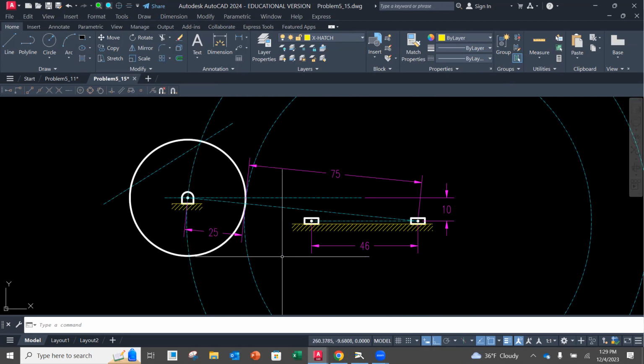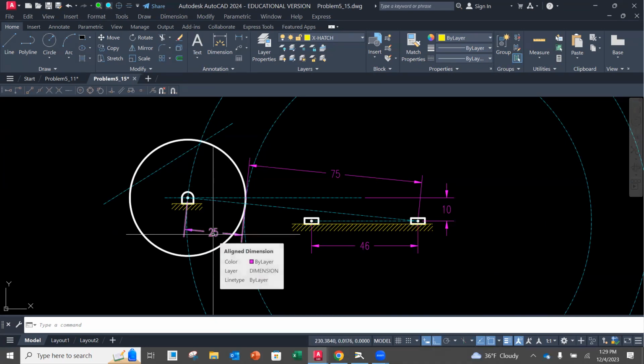So I wanted to lay this out so I knew about where my center of rotation would be. Then I picked a length of my connecting rod to be 75 millimeters. So when this is all laid out to my furthest out position, my radius to here is 75 millimeters. Now if my L3 is 75 millimeters, my crank is going to be 1/3 of that, so 75 divided by 3 is 25.